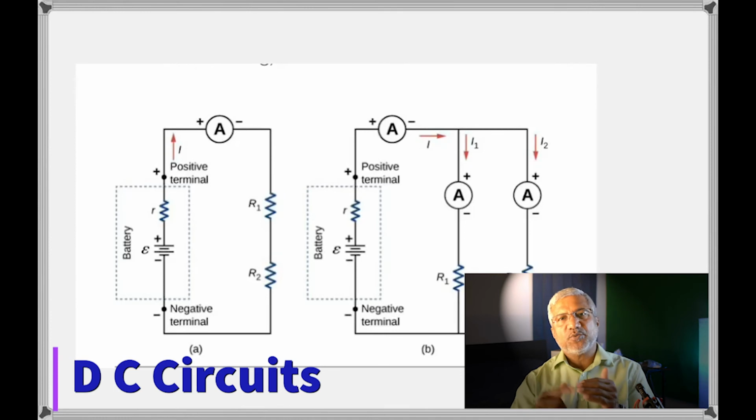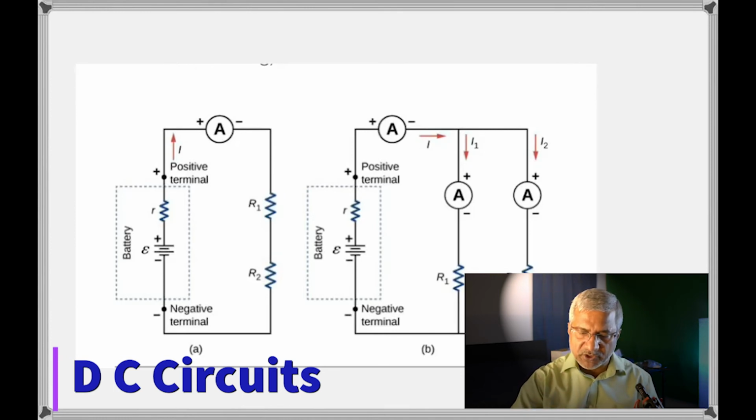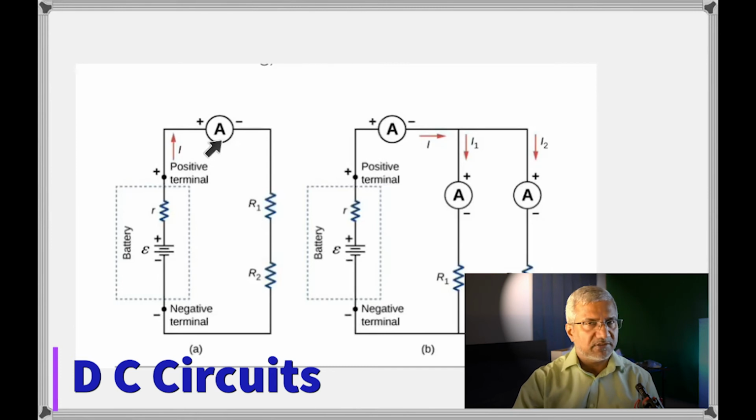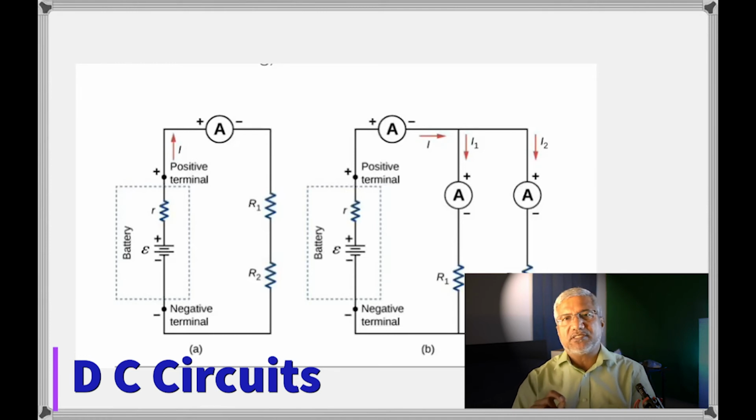Why? Because in series is when the currents flowing are equal. So again, if you want to measure the current through any resistance, you have to connect an ammeter in series with that resistance, so that the same current that flows through the resistance which you're trying to measure will also flow through the ammeter. It's very important. But then again, when you do that, wouldn't the resistance in the circuit be changed? You don't want that to happen. The introduction of the ammeter should not change the resistance in the circuit, because then it will measure a wrong current. Therefore, the ammeter is a very low resistance instrument. In fact, its resistance would be like 0.01 ohms, even smaller. So the introduction of the ammeter has negligibly changed the resistance and the current in this circuit.